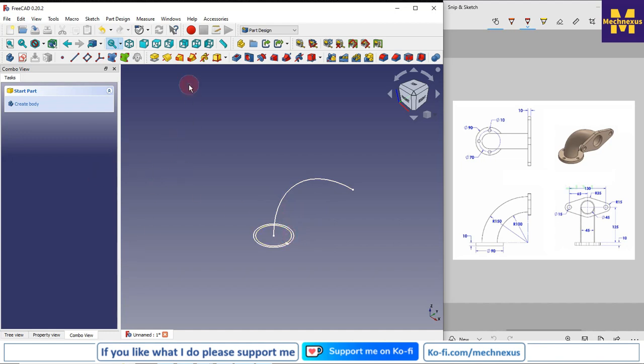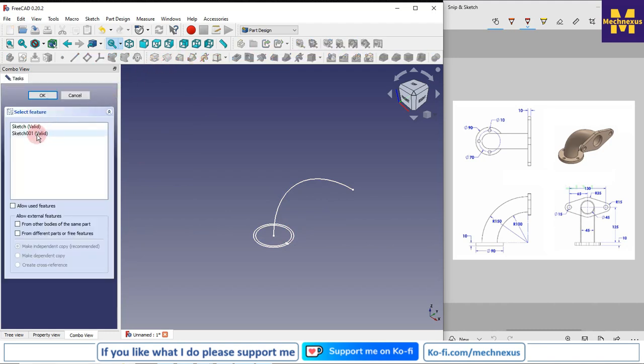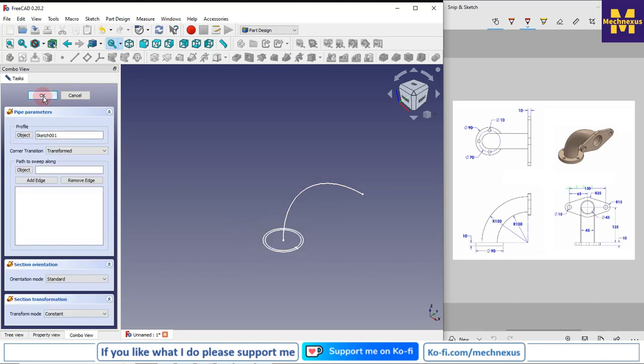Now we will go for the additive pipe feature. So we have the sketch and sketch 001. Say OK. Select sketch 001. This is the profile highlighted. Say OK. Now our object has been selected.